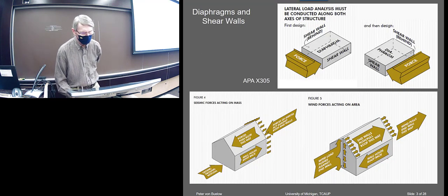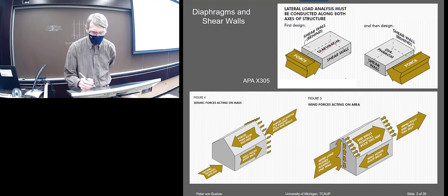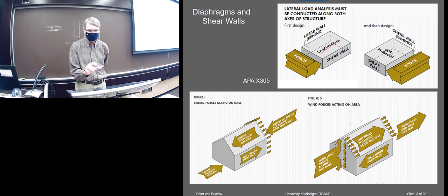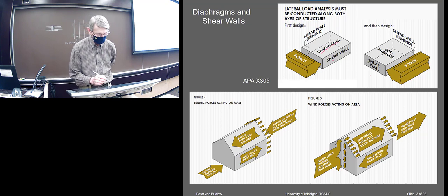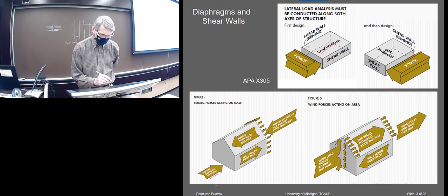So here we go, the force is applied. This is exactly what I just said. There's the diaphragm and here's the shear wall. Naturally, if the wind changes direction, it switches to the side shear wall, whatever resists it. Seismic forces, here, the ground seismic, would almost be in the reverse.